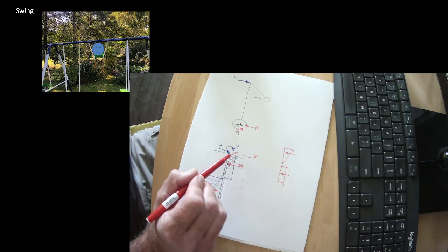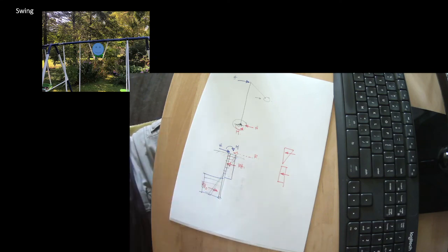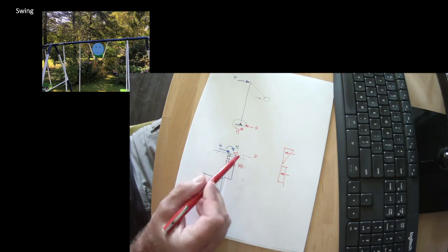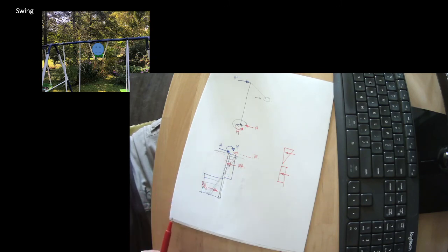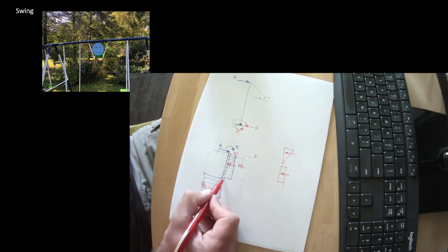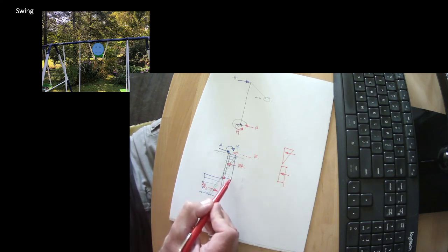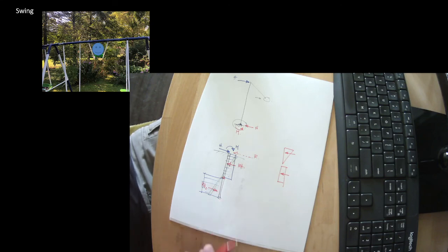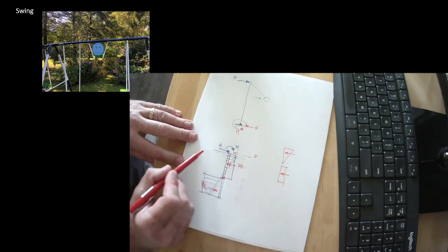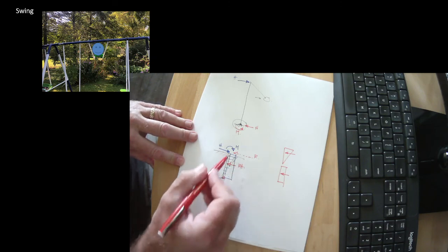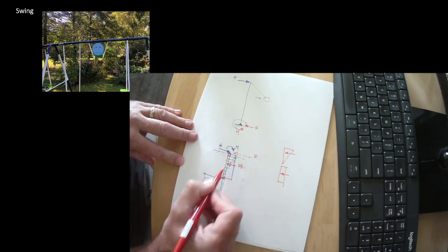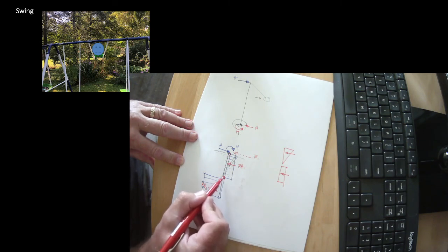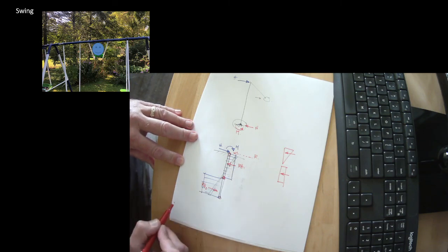But what we also know is that right at the very surface, there's no weight on the soil, and so it has no sideways resistance. So that's one thing. We also know that at the point of rotation, you can't jump instantly from a maximum this way to a maximum that way. That can't happen. So that's an approximation. So we know that there's going to be a smooth transition of bearing force that goes from 0 here. It's going to be 0 here because there's no movement at the point of rotation, and then it'll be at some value here.